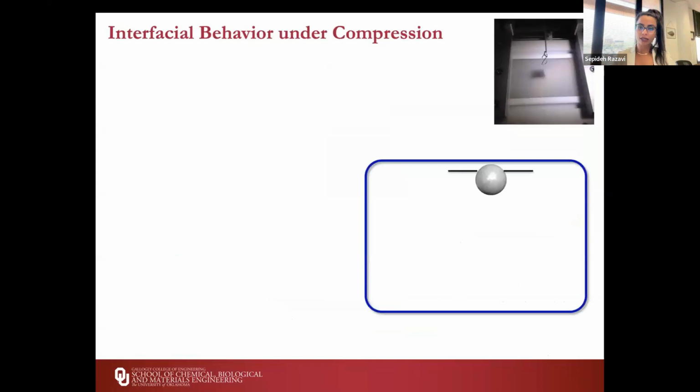Okay, so going back to this system of hydrophilic silica particles versus hydrophobic silica particles, now studying their behavior at the interface. The first thing we did, we put these more hydrophilic silica particles at the interface, and we are compressing from right and left to the center of the screen. And as you can see here, after the particles saturated the space available in 2D, they're going to get removed from the interface and get expelled into the subphase because we keep compressing and we are pushing them.